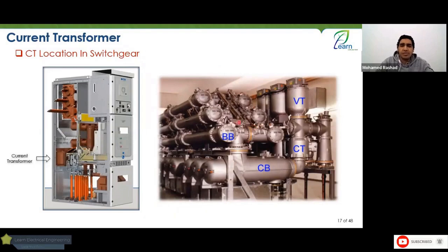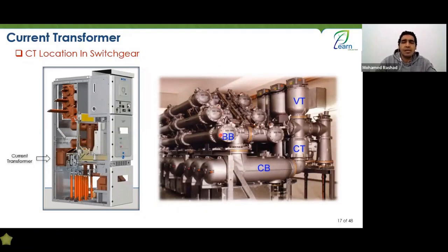Double bus, single breaker. But of course, it is a 3-pole, as you can see, meaning each phase is supported on its own pole. So you have a current transformer, and there is one here, as you can see. This is a pole, but only after the breaker. However, sometimes it is both before and after the breaker.